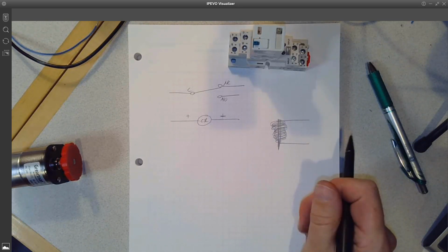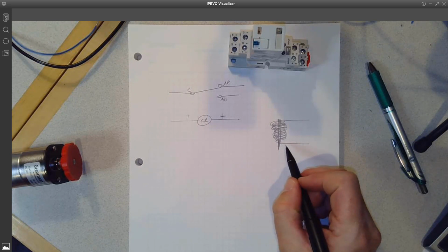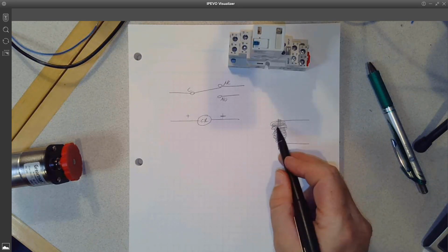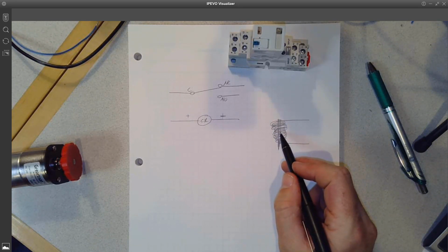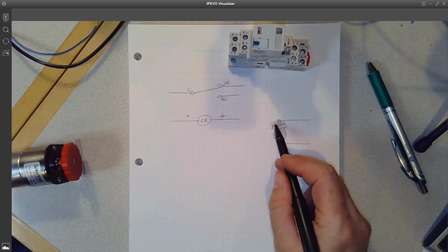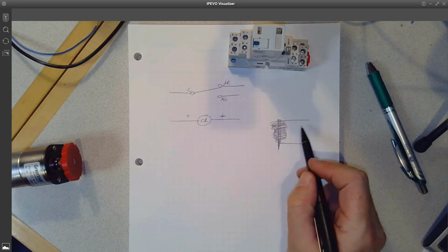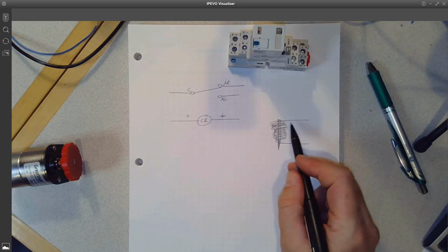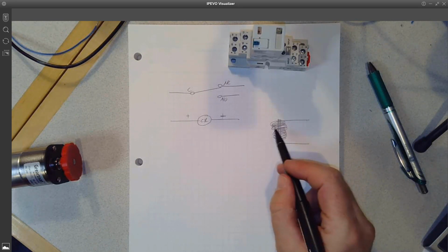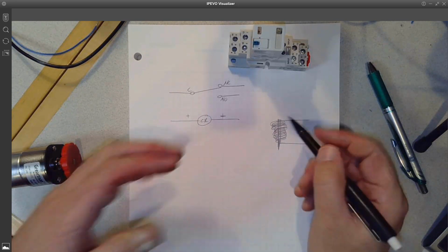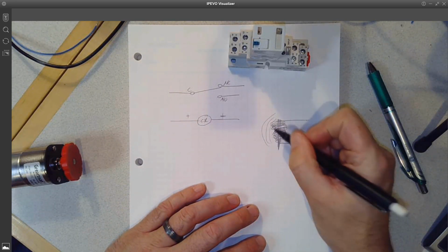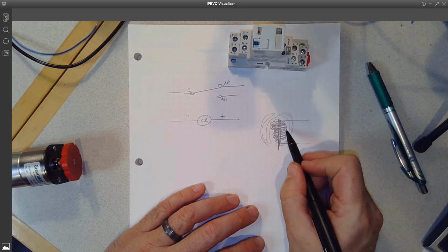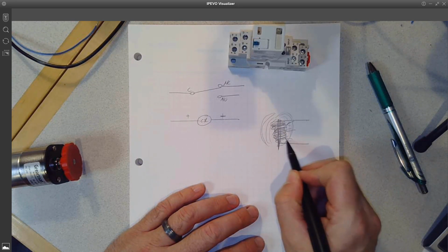I showed you an example of that in last week's discussion. So when we're using the field to move the armature, we're using current flowing through the inductor to create a magnetic field. When we remove that current by turning off the relay, it works backwards. Now that magnetic field that was created by the current, if you think about magnetic fields, are kind of loops, right, north and south poles. Now that field is going to collapse down.